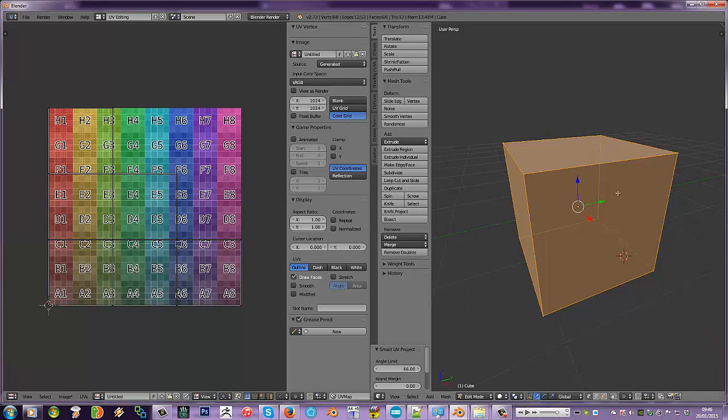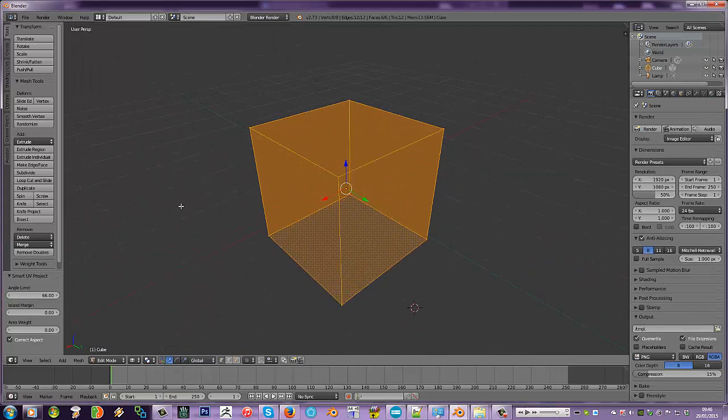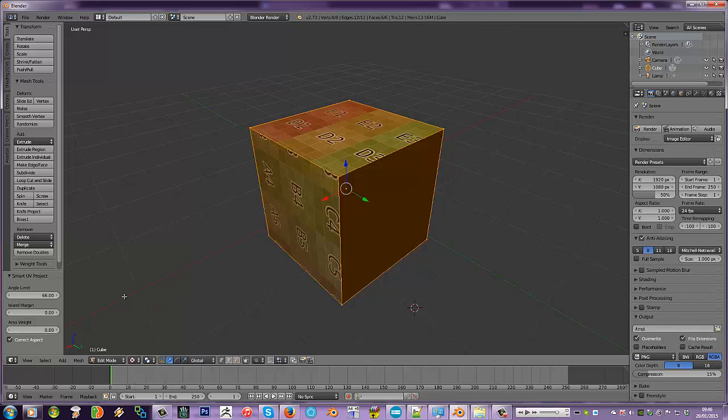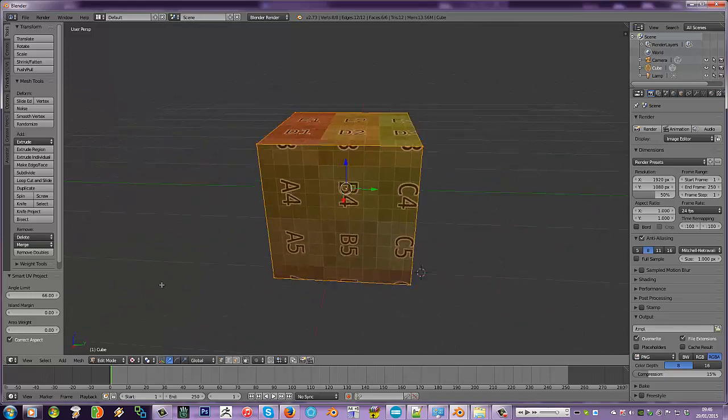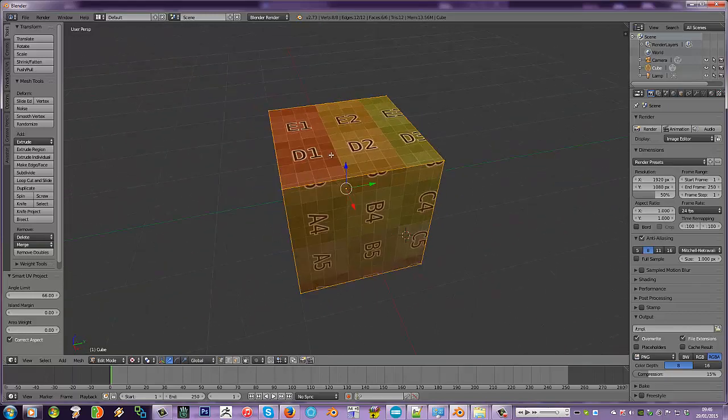Now you can't see it by default because we just set to just shaded mode. So let's go back into default view, up at the top, default view. Now we need to change our display mode to see the texture we've just loaded behind this. So to do that, we change it to textures in the viewport shading, and now you can see the texture on the model.